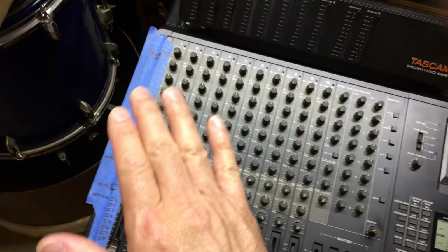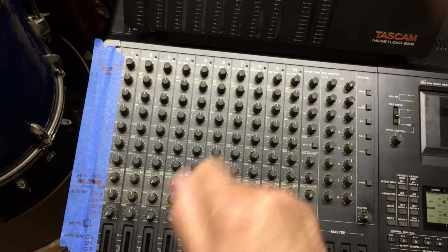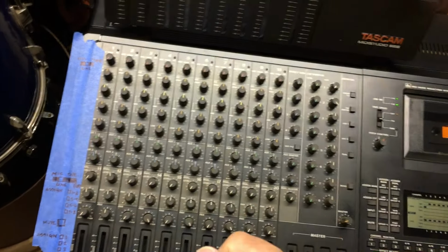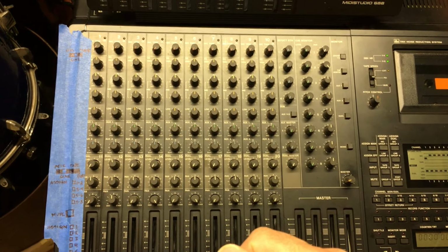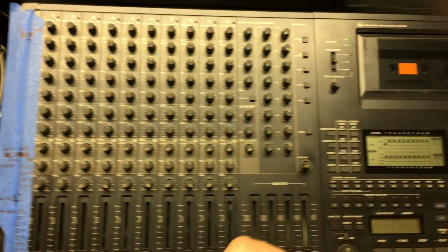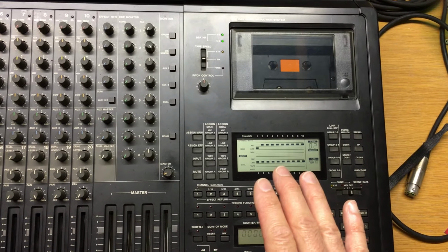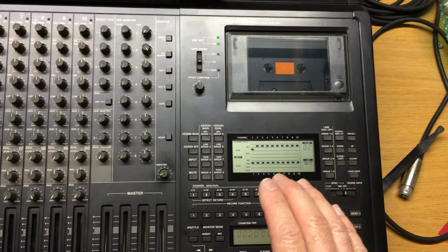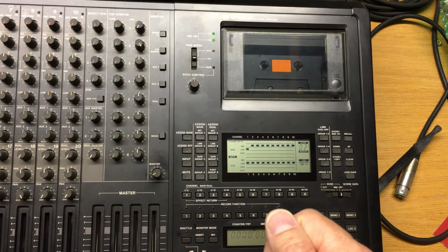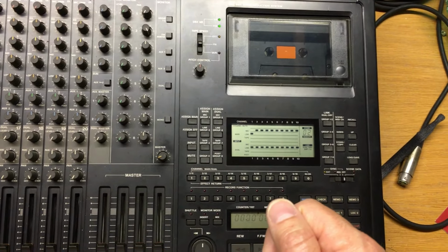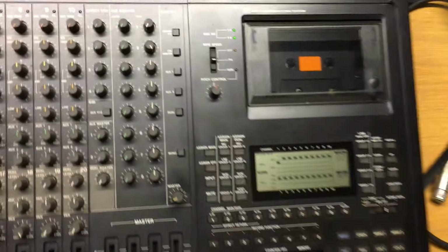If you had mechanical switches for all this stuff, how many of you have dealt with older mixers where you've got to exercise the switches and, you know, squirt contact cleaner in them, and they get old and futzy and you've got to mess with it if it's been sitting for a day or two. You don't have to deal with that when you have electronic switching. The switching is silent and you don't have mechanical contacts that get oxidized or corroded or soiled and fail. So that's a plus for this.